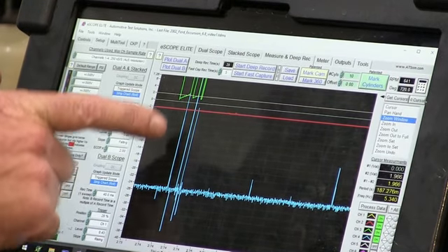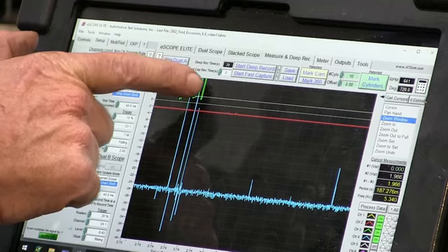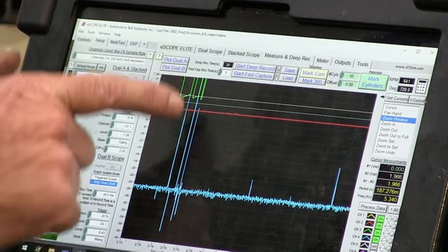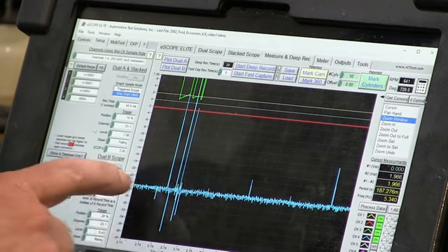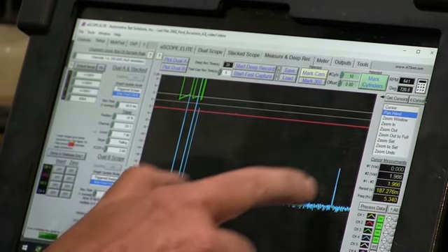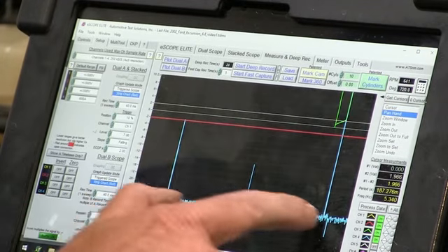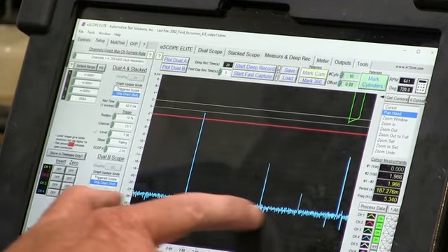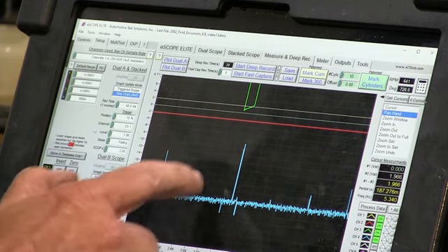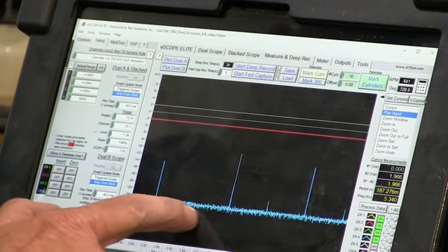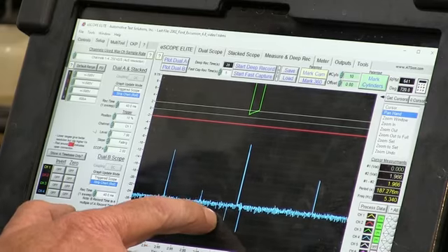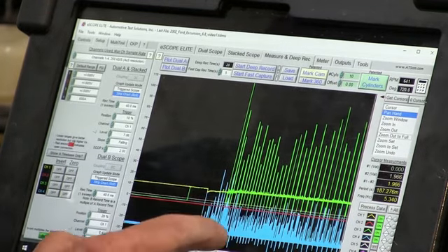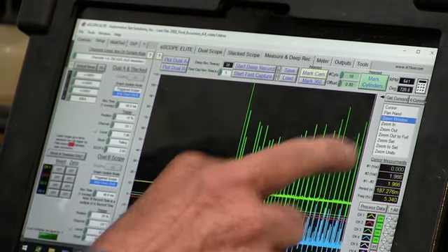You see these big strikes that are coming through that line up with that number 9 coil? This is on the negative battery wire. Do you see how none of the rest of these are that big? You see some because current always has to go back to its source, but you can see some of these are bigger.